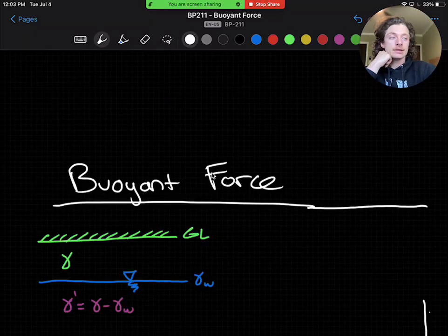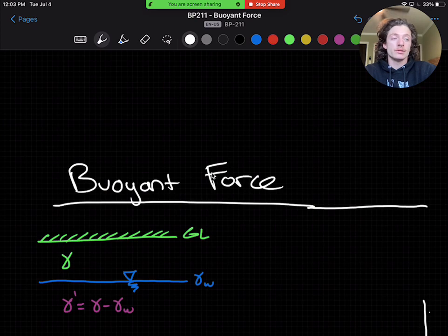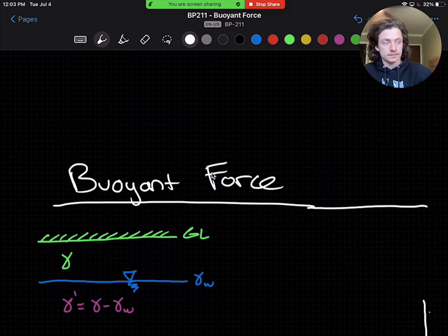In previous lectures, we've discussed the effect of the water table on the unit weight of soil, creating an effective unit weight that in turn alters the active earth pressure. Similarly, a high water table will also have a buoyancy effect on the abutment. I like to consider the water table conservatively in these two ways.